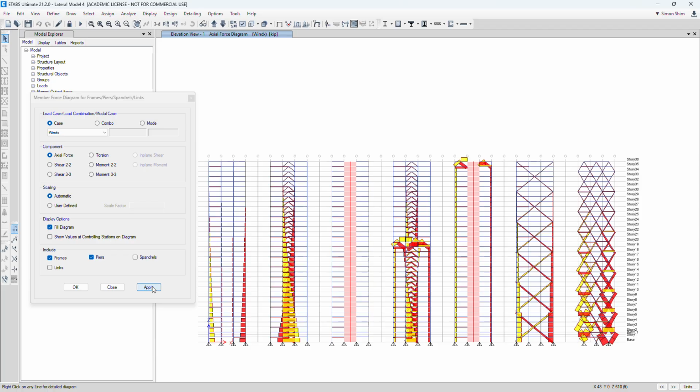Since we have an outrigger column and outrigger truss, and also still continue the backbone of the shear wall or braced frame, loading is redistributed between the coupling forces from outrigger column to column and within this braced frame. So you're going to see this same force distribution in the current model.